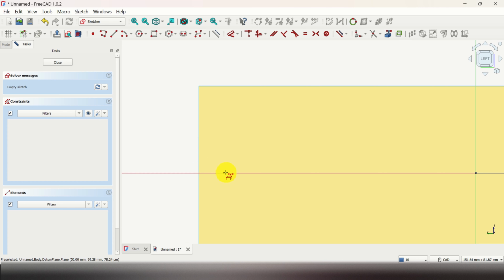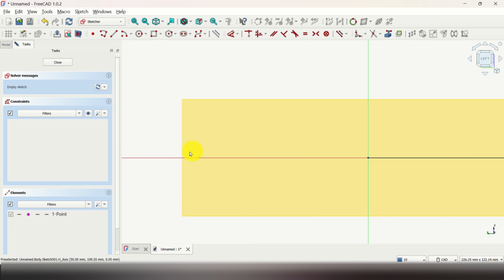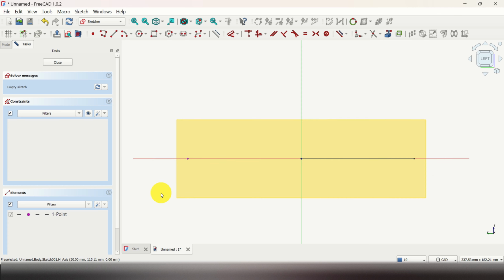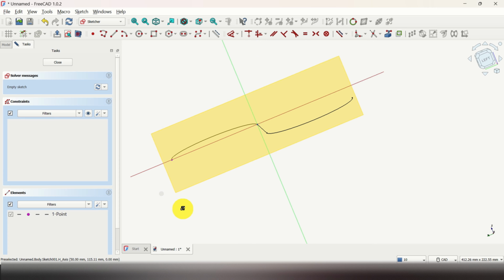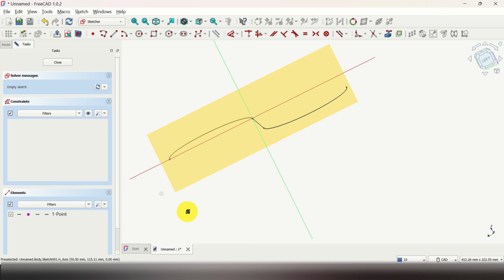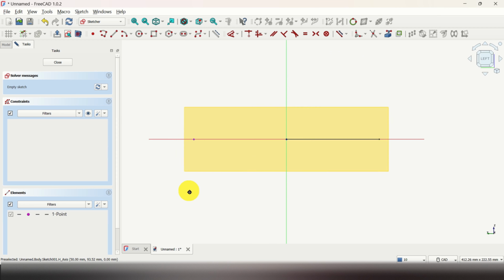So click here and click on this point over here and voila, you can see that the point appears in our sketch. Do the right click and let's create a circle over here. However, it's still a good idea to rotate everything and to see that this point is indeed the point we want. It is. So let's click on left and let's continue.